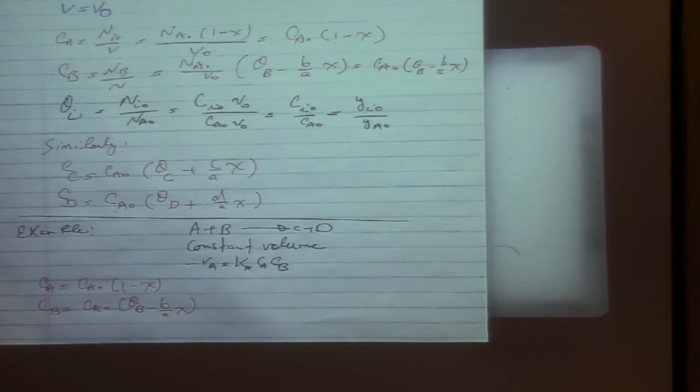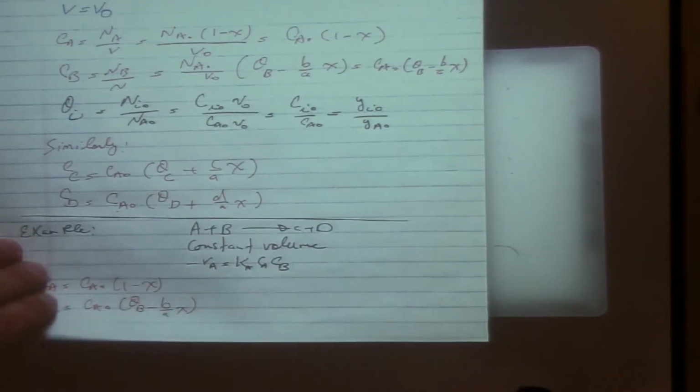You will define a parameter called epsilon, and then you have to calculate epsilon and put it here. That's for the gas phase when the volume changes. So basically, the type of stoichiometry changes. Otherwise, the same regulation holds through, starting with the design equation, then kinetics, and then stoichiometry.